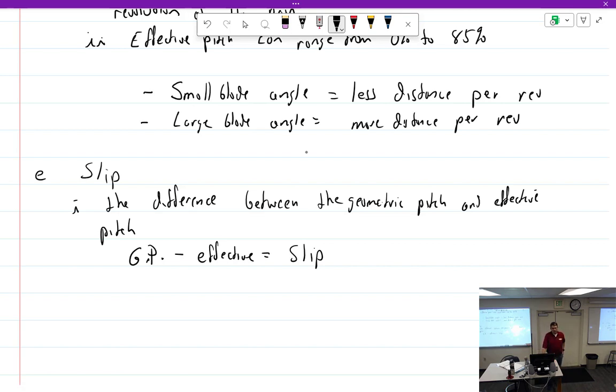Why is this important for you to know as an airplane mechanic? It's not. What is important to note is how a propeller and the engine combination react to what's going on. We've talked a lot about static RPM. If you're going to work on something with a propeller and a fixed pitch piston engine, you have to understand the static RPM correlation. And then you have to understand what happens to the propeller as you start to roll down the runway, no matter what propeller it is. If it's got a prop, you need to understand that correlation.